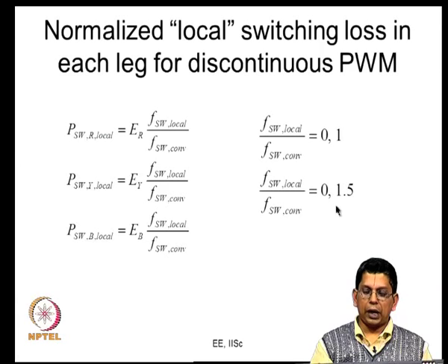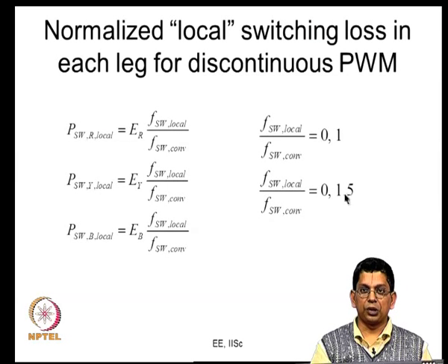Okay. So, actually if you increase the carrier frequency like this, then your device is switching at the same average switching frequency, but you will be able to achieve better, lower harmonic distortion at high modulation indices. This is also a fact which we have studied and it has been widely reported in the literature. We also saw a few paper references which talk about this.